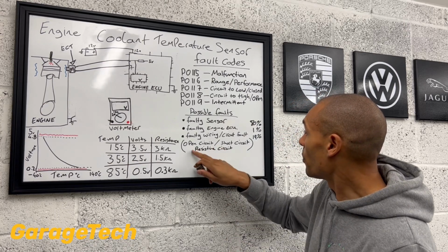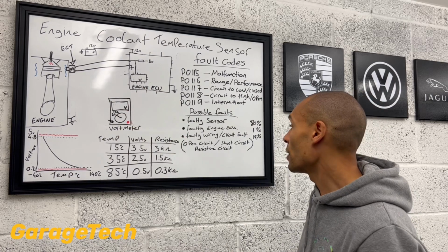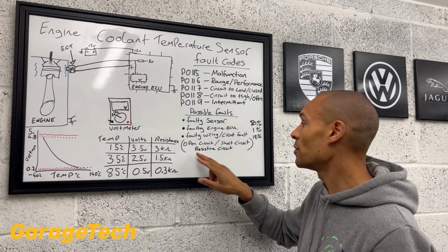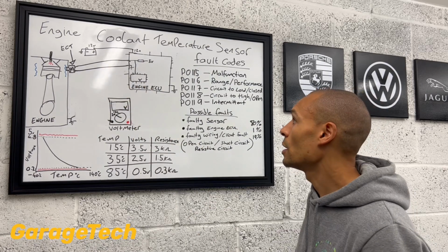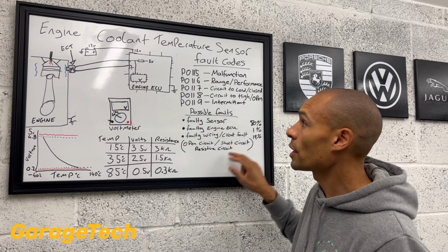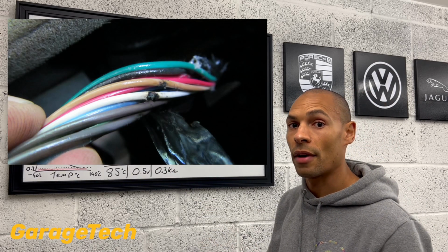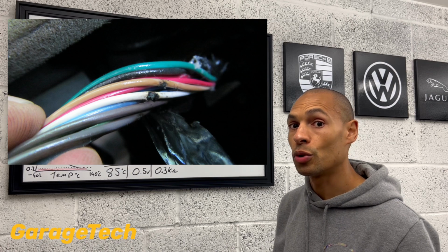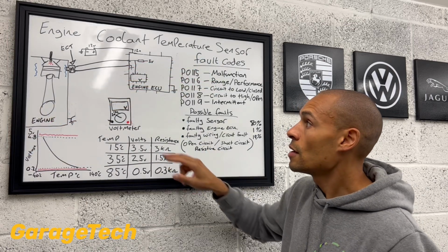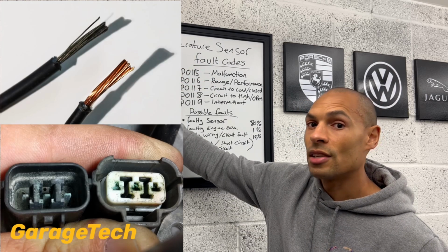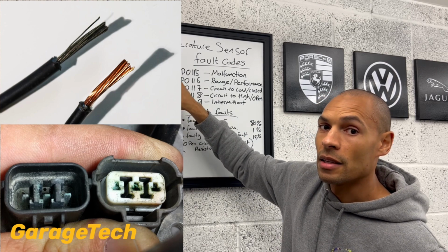So as I've got on here at the bottom with the wiring, typically with the wiring circuit itself, you've only got really 3 potential faults. It's either going to be an open circuit, which basically means there's a break in the wire, so the wire's broken. A short circuit, that means that potentially 2 wires are touching each other, or it's touching the frame or body of the vehicle, so you might hear the term short to earth. And then the other one is a resistive circuit, so there's some form of additional resistance in the circuit which is then causing the reading that the engine control unit gets in to be slightly incorrect.